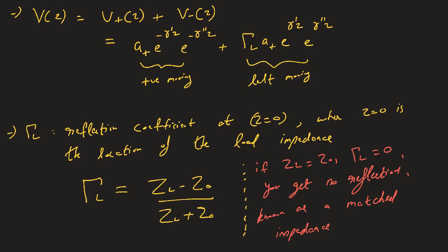So when we looked at the reflections at a dielectric, we saw that the difference in refractive indices back then determined how much of the incoming light reflects, and over here the difference in the impedance dictates how much of the light reflects. It's a very strong parallel, and transmission line theory draws very strong parallels to Maxwell equations, right? It's an abstraction on top of those.